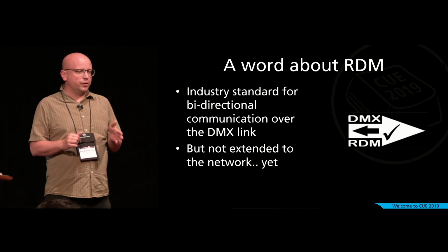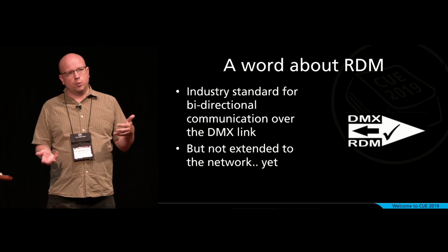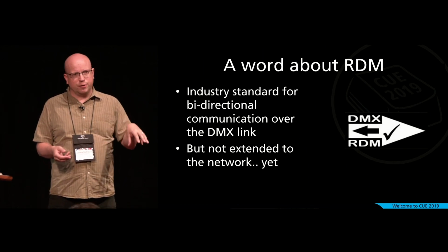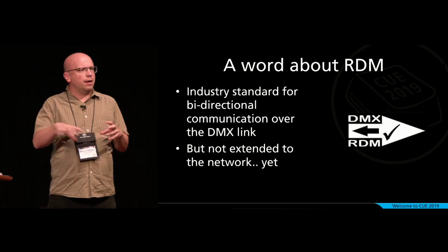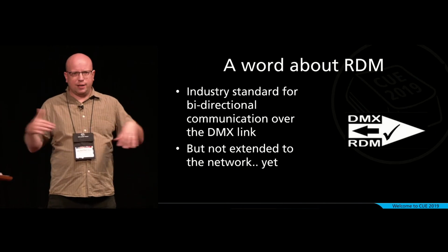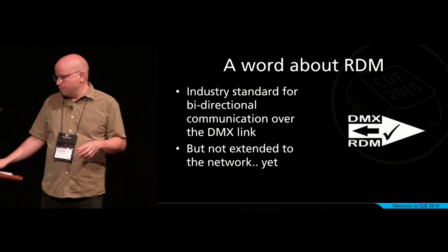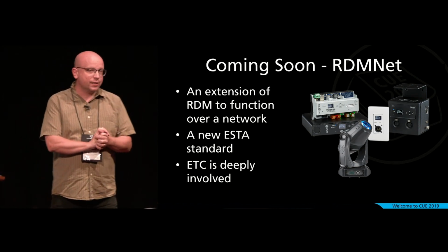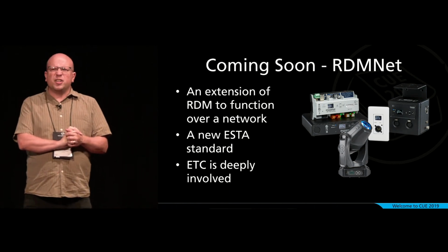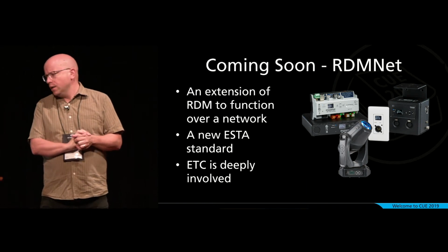At the moment, there is no standard way to do RDM over network. Everybody's kind of done it in their own way. We've got a way of doing it over ACN. There's a way in Artnet that they do it. There's a way that MA lighting does it. None of that is compatible. It's all kind of proprietary. But RDMNet is on the way. So RDMNet is kind of like streaming ACN for RDM. You can kind of think of it that way.